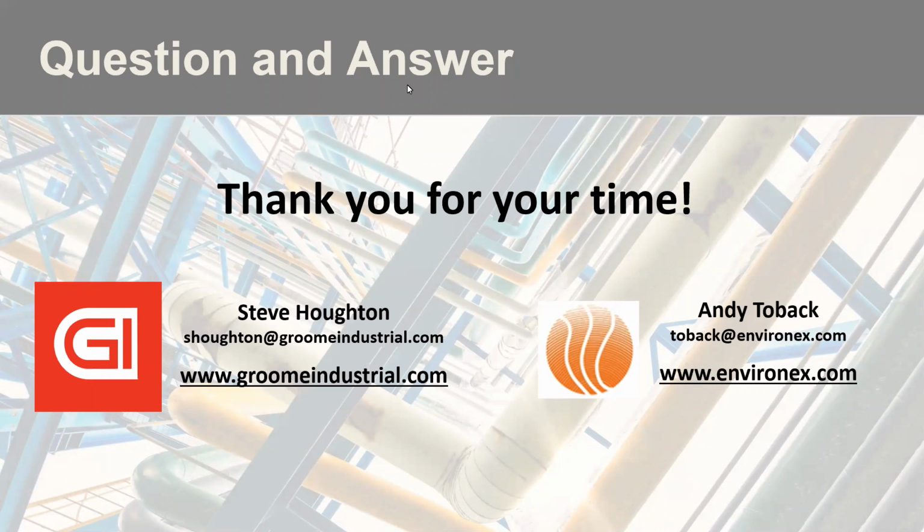Correlation on a theoretical efficiency. Is ammonia efficiency a function of the theoretical efficiency in the lab versus the field? How would you monitor for ammonia efficiency? And you touched on this in one of your slides here, Andy, but looking for a little bit more specific explanation here. Yeah, I mean, if you know your exhaust flow, you can calculate the ammonia ppm to your SCR